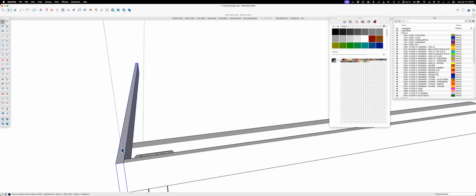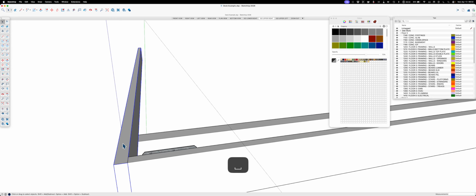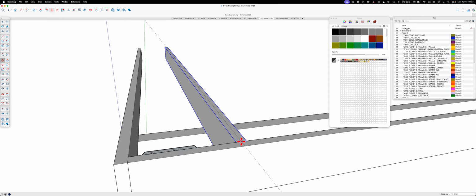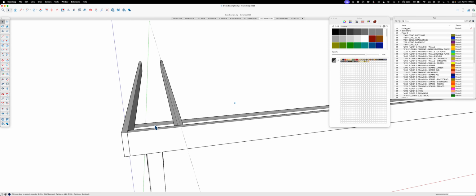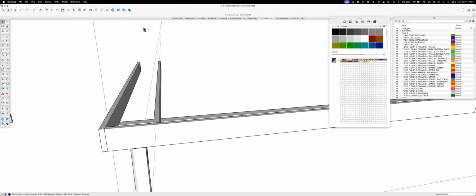So let's do this. Let's do the letter T. We'll come over 16. Now, if you're doing angled decking, look at your manufacturer, your vendor, because they may want closer spacing. They may want 12-inch. Most of the composites do, because it's kind of a big span for them. It'll feel spongy. All right, so we've got this centered on 16. I'm going to get rid of that.